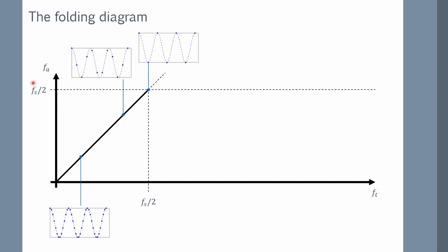Even if you're sampling at a low frequency, let's say a few kilohertz, you still have gigahertz noise in the signal, due to electronic noise, due to picking up radiation from radio and whatever. So this content at very high frequency is still there in the signal unless you do something in the analog domain, which we'll discuss. Which means that everything else here that we can't resolve has to appear in our spectrum, because it still changes the location of the samples.